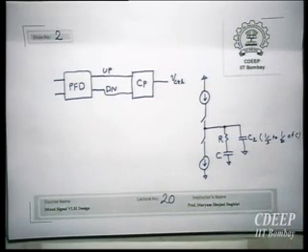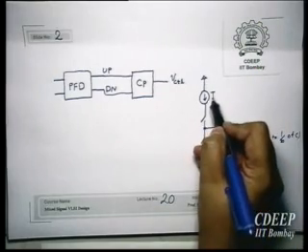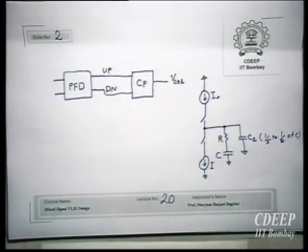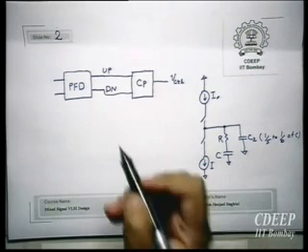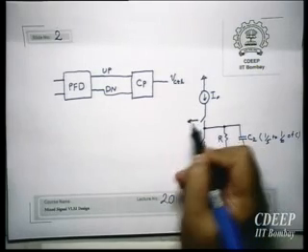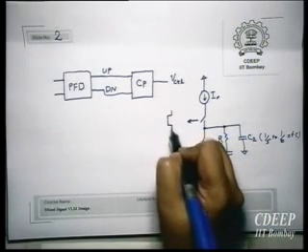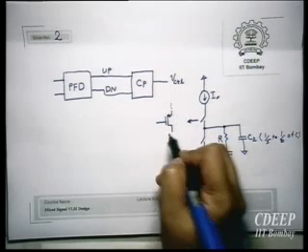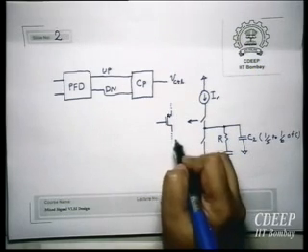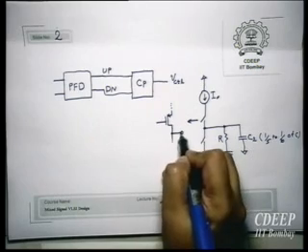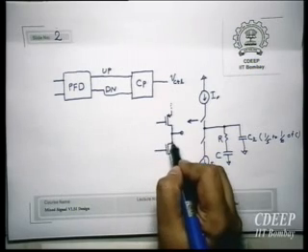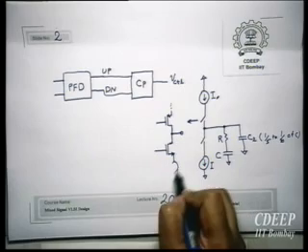Now these switches will be MOS switches, and these current sources also will be MOS current sources, as long as we are talking about an integrated technology. So now if I replace them by switches, here I will have, for example, a PMOS transistor connected to the source current source, and on this side I will have an NMOS switch which is connected to the same current source.